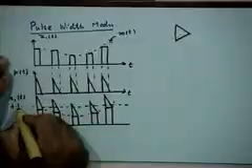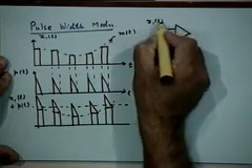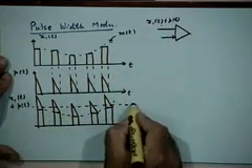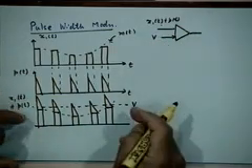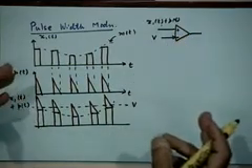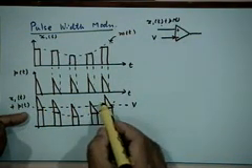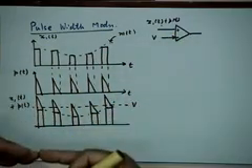One of those inputs is this signal, which is x1(t) plus p(t), right? So that is one of the inputs, x1(t) plus p(t), and the other input is a reference voltage, which is equal to this constant voltage, let's say V, right? So the output of the comparator will be a positive output when the input signal is above the threshold value, above the voltage V, and will be either 0 or negative depending on how you design the circuit. Let's say it is 0 when the input voltage is less than that, right?